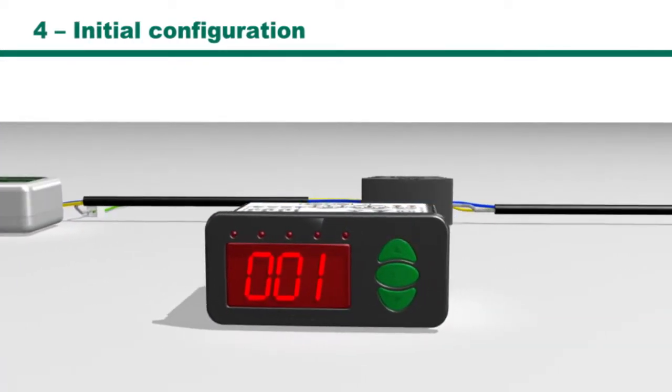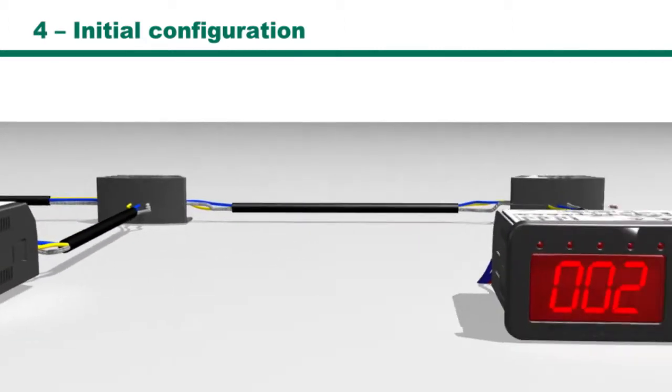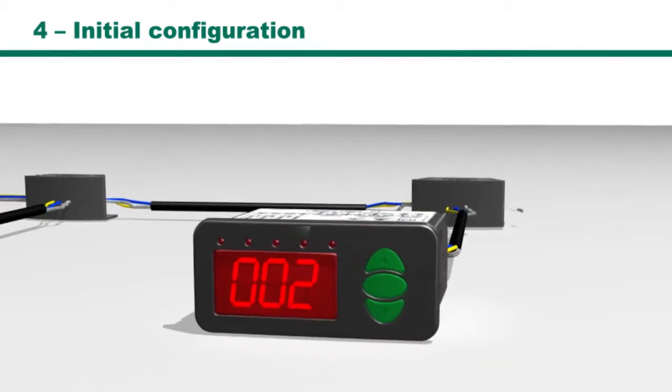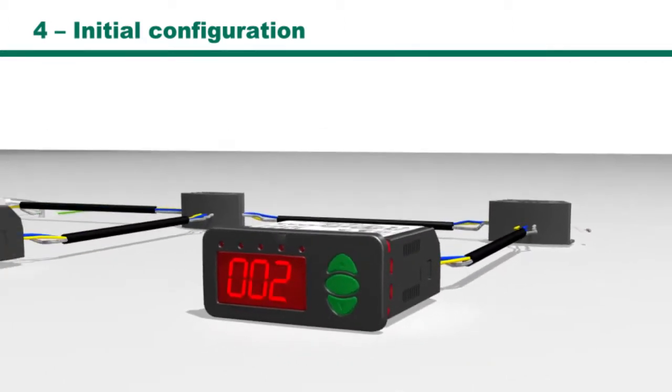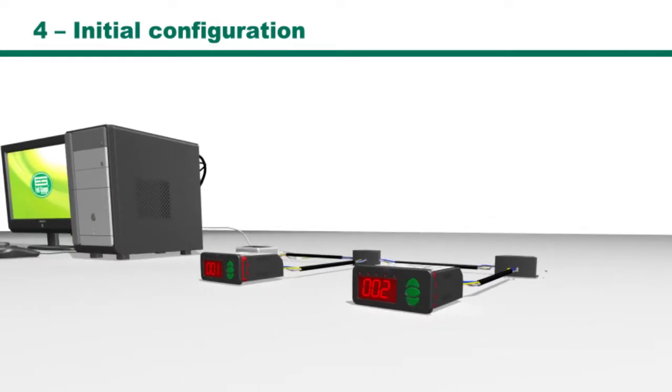Before you start configuring Sitrad, make sure the instruments have different serial address parameters. Refer to the manuals of the controllers to learn how to alter the address parameter. Until the beginning of this training, the serial address is the last parameter of the setting list in all controllers.